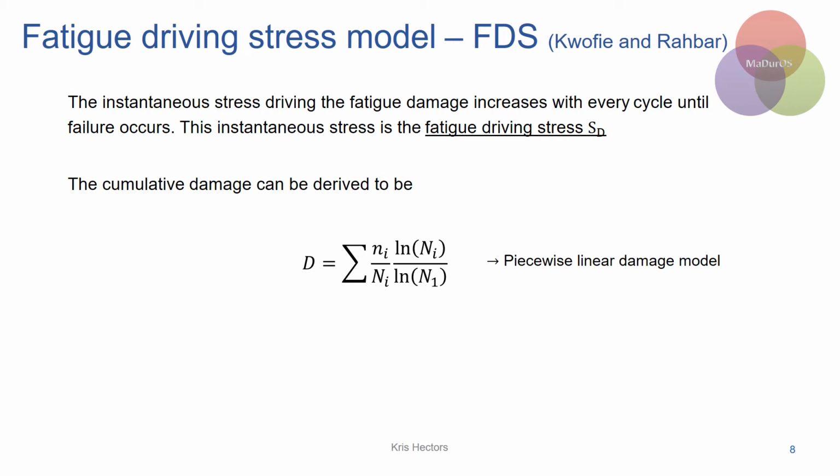As mentioned in the previous slide, the fatigue driving stress approach is a piecewise linear model. The approach is essentially a modification of Miner's rule where load sequence effects are included through a logarithmic ratio of the constant amplitude lifetime of the current loading block and that of the first loading block.